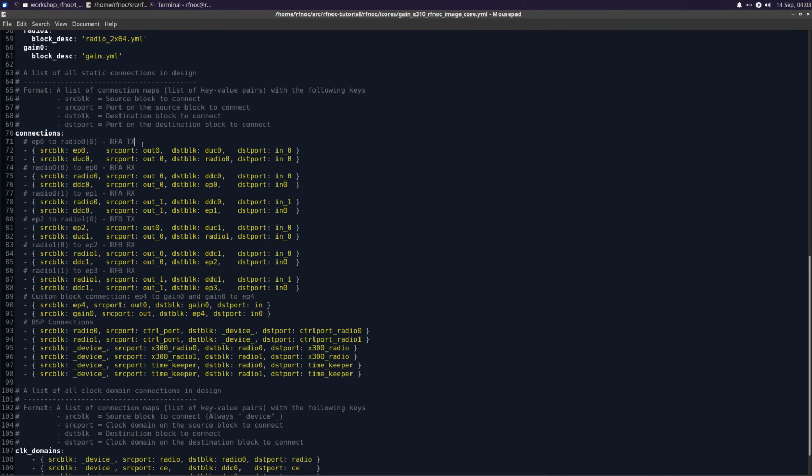So you want to go to the DUC, to upsample them to the right sampling rate for the radio. And that static route is incompatible with, conceptually, if we try to put the DUC in between the radio and the DDC. There is no route defined here. And we could edit this to add that route. But as I said before, if we really wanted that functionality, we'll just have every block correspond with a stream endpoint. And then that way we can interchange these at will as needed.